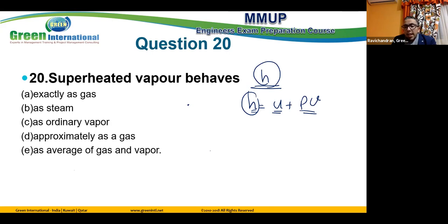So if you need to calculate anything related to cycles or equipment like a compressor, evaporator, condenser, turbine, pump, boiler, whatever, heat or work for this equipment, the main idea is the difference between two enthalpies. So you need enthalpy before, enthalpy after. It means energy before, energy after, minus the difference. You can get work or heat according to the type of equipment, whether it gives heat or gives work, or you need heat or work. Clear? So one of the important things is enthalpy.